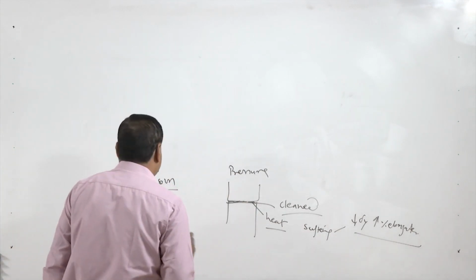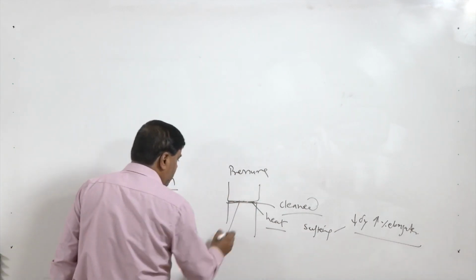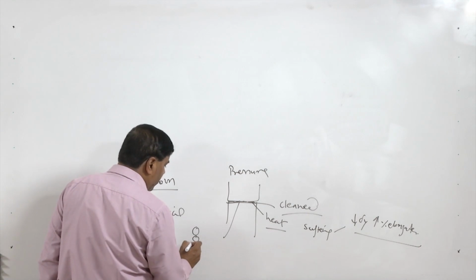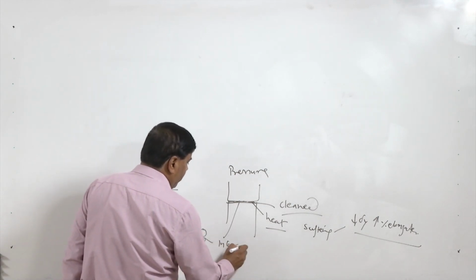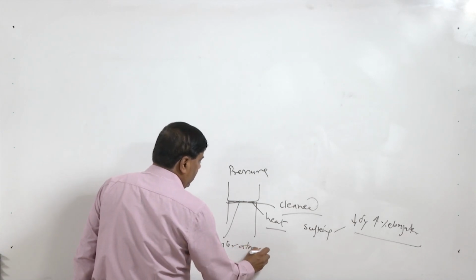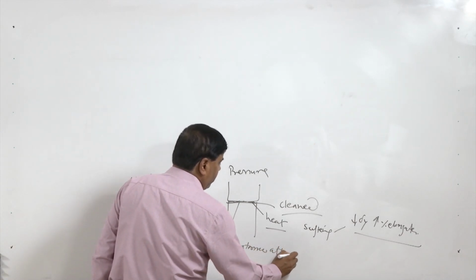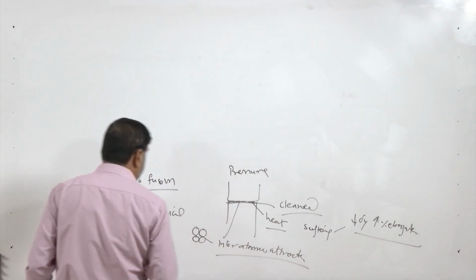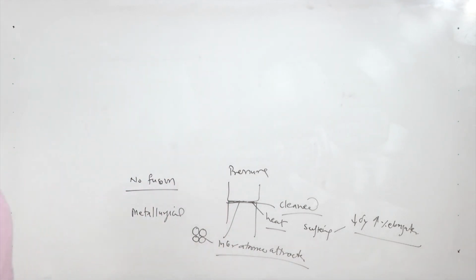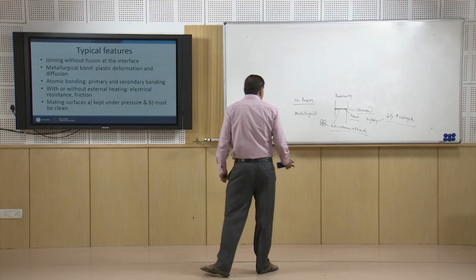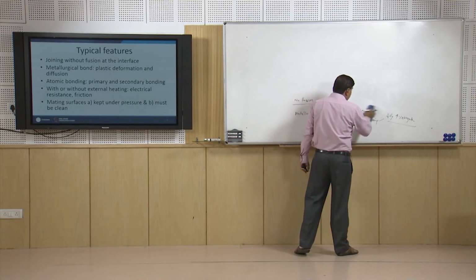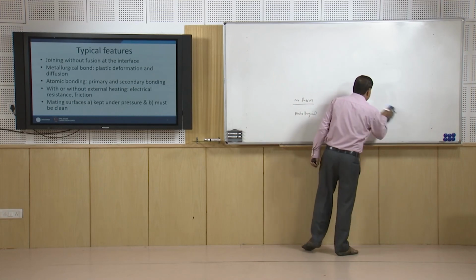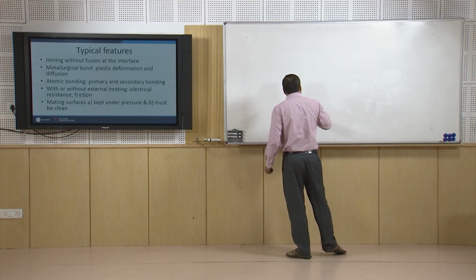metal to metal contact, and whenever it happens, the atoms will come into extremely close range, so that by the interatomic attraction the bond is formed between them. So, basically the bond is metallurgical, which is achieved through either plastic deformation or the diffusion across the interface.